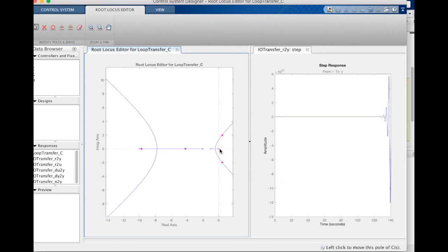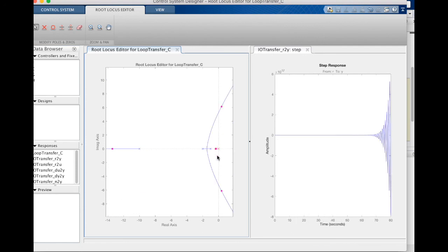We notice when we did this, that completely changed the shape of the root locus. That's exactly what we expected. Now we've got root locus going off at these 45-degree asymptotes. So we really need the zero to be placed as well to get back something similar. You can just visually place it here. We can just click and place a zero wherever we want. And if I zoom in a bit here, I'm going to move that in a little bit.